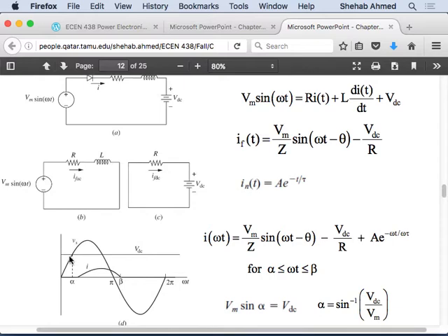Will it give you the same solution as alpha? No, alpha is where the DC voltage intersects the AC voltage. So this is a defined value. In the function I of beta equals 0, alpha is also a solution to the problem. So alpha is another point. Yes, but remember numerical methods: you typically have to give a starting value. I don't know how you do it in your calculator, but generally in numerical methods you have to assume a starting value. So if you get two values, you may get this value and then you may get this value. So you know that it's not the alpha.